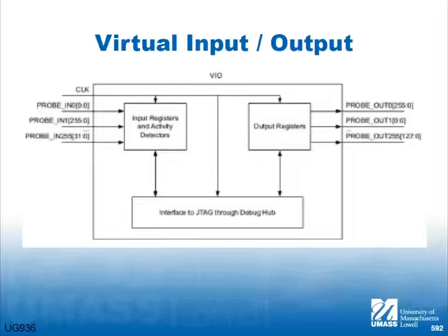What I could do is take the groups of signals and multiplex them. And the input to the multiplexer is the output of the VIO module. Isn't that cool? So now I can write a value, and not a lot. Let's say it's 4. So I write a value 0, 1, 2, or 3, and it selects a multiplexer that puts the proper set of inputs into my internal logic analyzer.